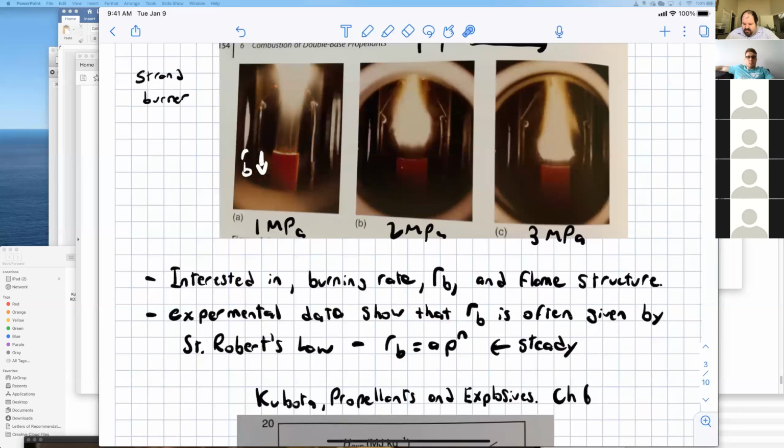So even if you burn all of the propellant, you're not going to change the pressure that much. They can essentially determine the burning rate of the propellant as a function of pressure by burning multiple sticks at multiple different pressures. After they do that, they fit a functional form of this a P to the n type thing. This is very common, and for a lot of propellants, you can look these up if they're publicly available. For many of them, they are not.